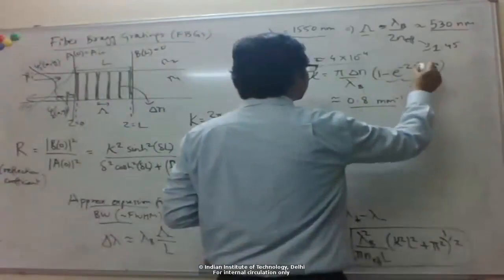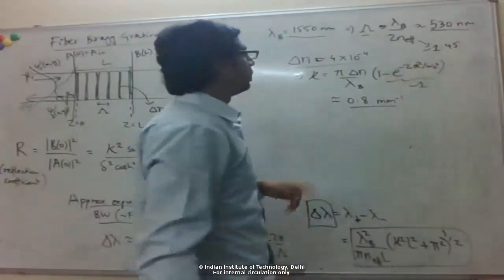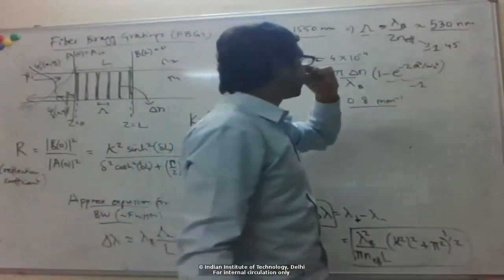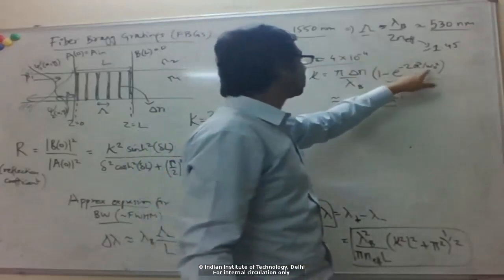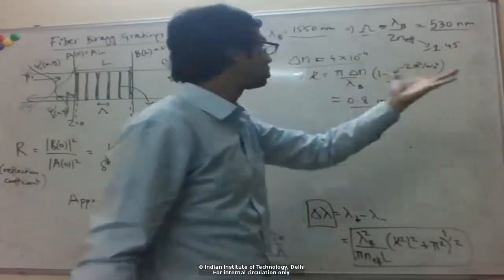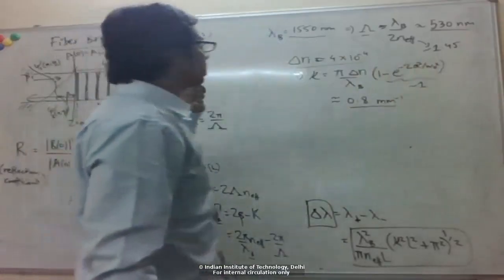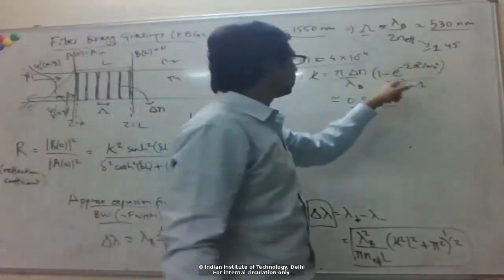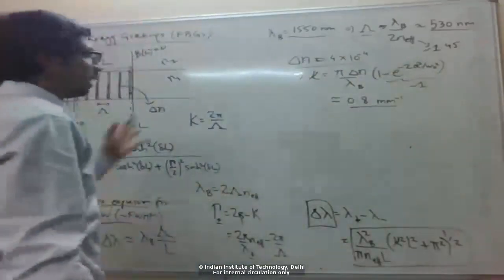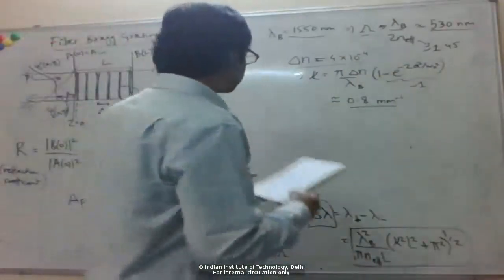You can also explicitly calculate this, right? We know, for example, we have approximate empirical expressions for W0 over A in terms of the V number. So for given fiber dimensions and this wavelength, we can calculate what this would be. Typically it's between 0.5 and 1.